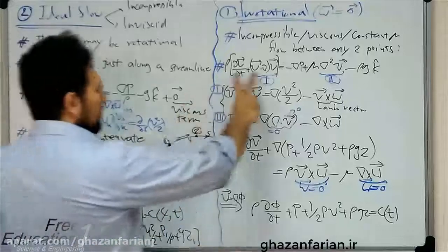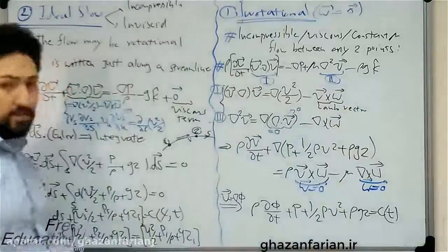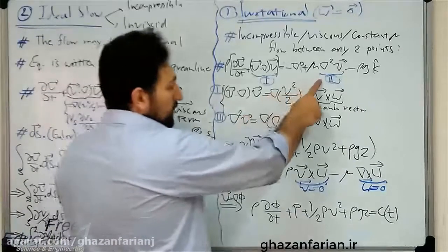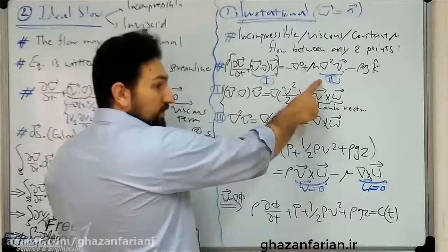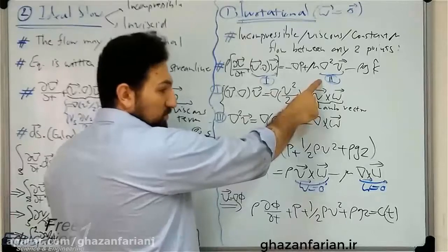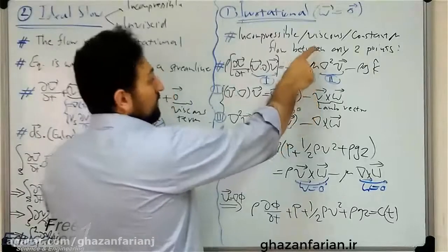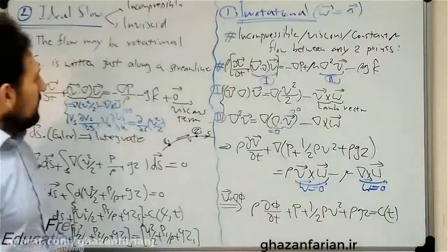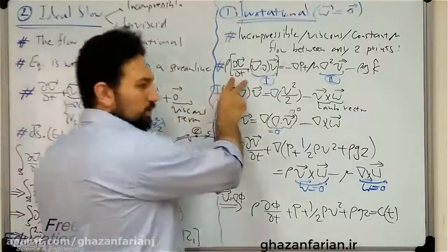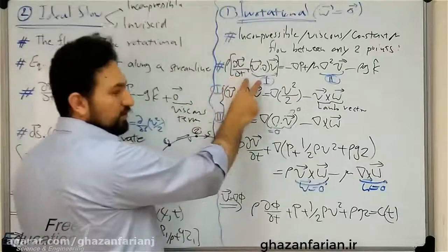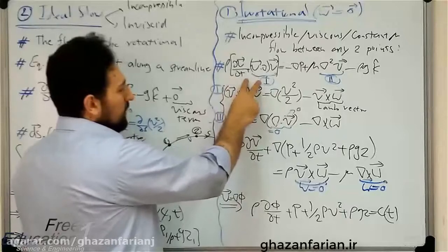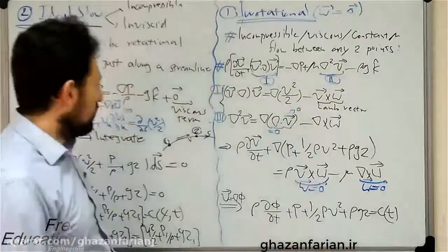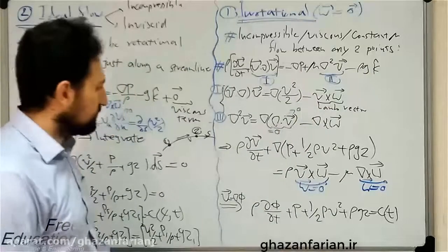Okay, let's start from the Navier-Stokes equation. Now you see that this term here is the viscous term, so I included the viscous term in the Navier-Stokes equation. So the flow is viscous. This one is the local derivative or local acceleration. This one is the nonlinear term or the advection term. Then the pressure term, the viscous term, and the gravity force or the volumetric source term.